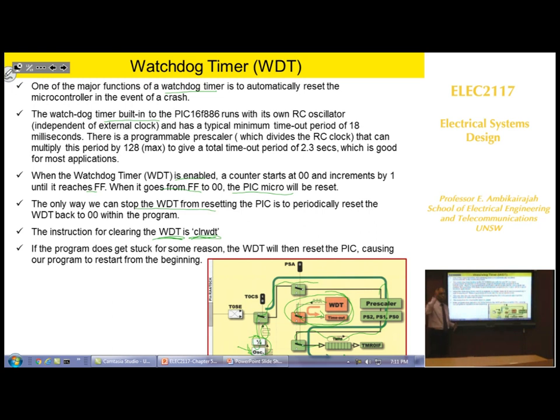Otherwise, it will run for so many seconds and then it will reset your program. You don't want that to happen. If the program does get stuck for some reason, this WDT timer will then reset the PIC microcontroller, causing the program to restart from the beginning.